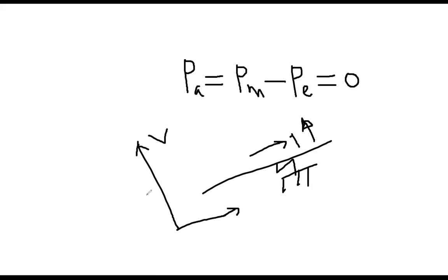but if you look at the voltage during the short circuit, it might go very low, even close to 0. That is the impact of the fault. So voltage will be significantly low. Now here you might notice that the power is going very close to 0. That is the thing I am asking: during a fault, current increases and voltage decreases, so this should not change. But then it goes close to 0. Why does that go close to 0?